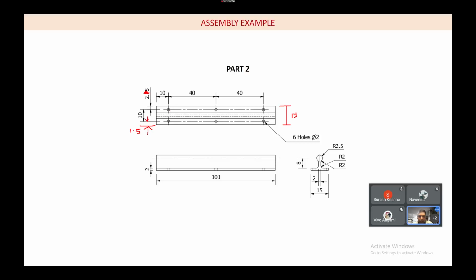So spacing is 40, and I'm going to 3 instances, and here I'm going to select this, switch the direction, and 10 mm. Is it 10? Yeah, it's 10 mm spacing, so center to center. So dia 2 holes, so we have done. So let us give the OK. So now we got this also. Okay. So now we will save this as rail.